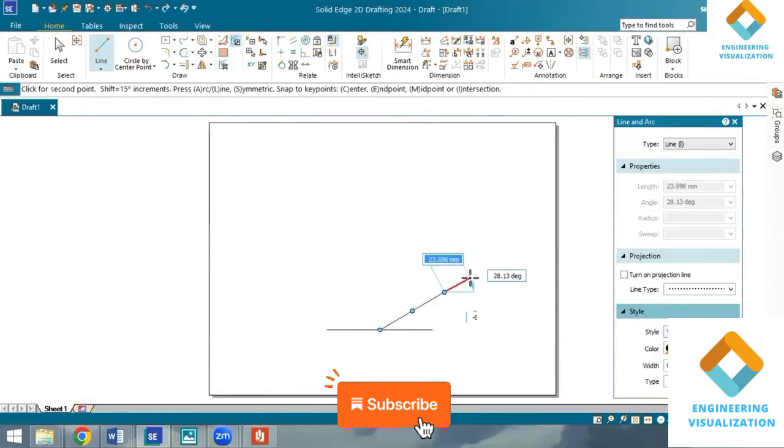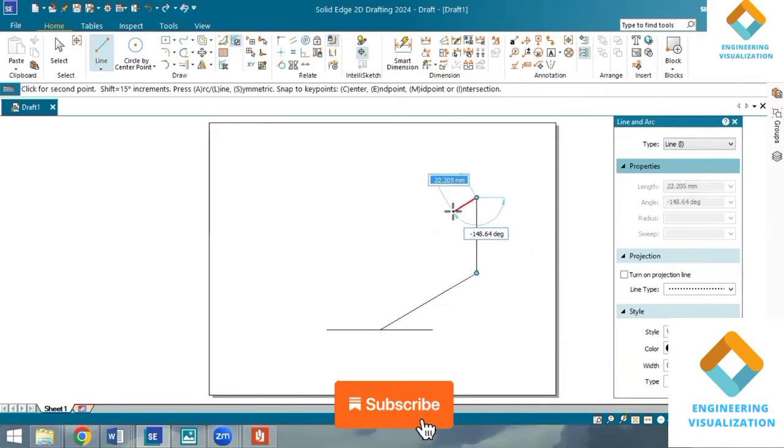Here the rectangle block having base edge 30 mm at 30 degree and vertical edge 60 mm, angle is 90 degree. Again length is 30, angle is minus 150, and then vertically downward is joined with a length of 60 mm.